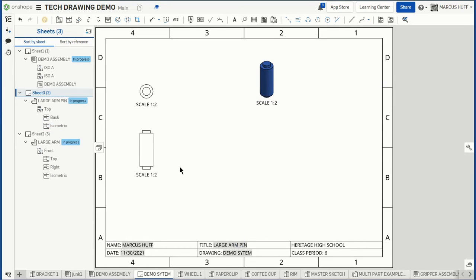And then if we want to do some measurements, if you're talking about circles and arcs, do the ones where you see it. Don't describe circles and arcs with linear measurements. So there's a diameter there. I usually work from the outside to the inside and kind of line them up like this. These leader lines need to be angled when you're showing these.